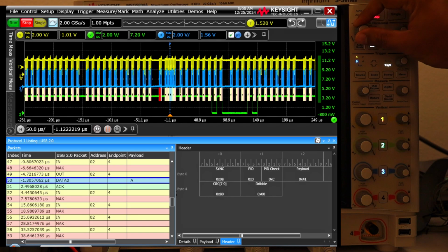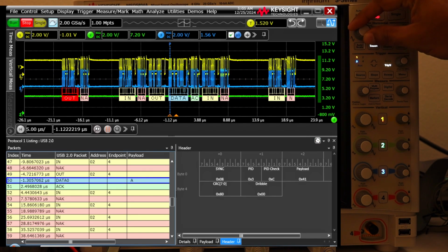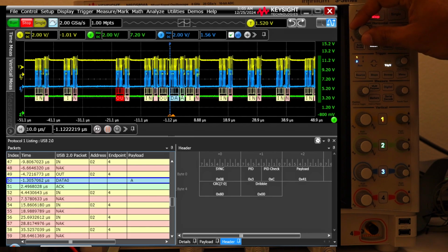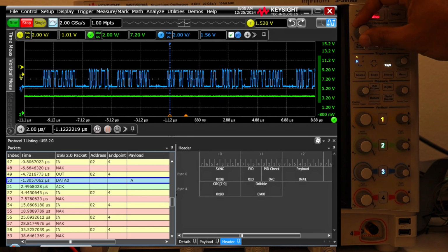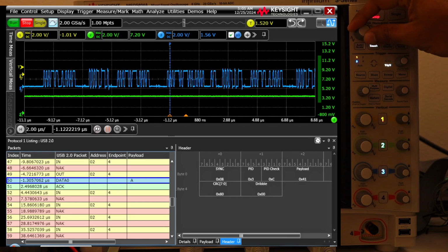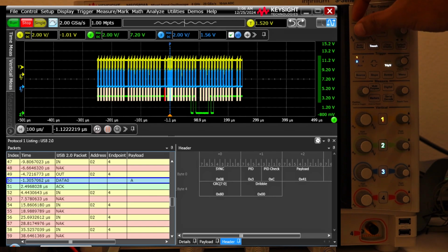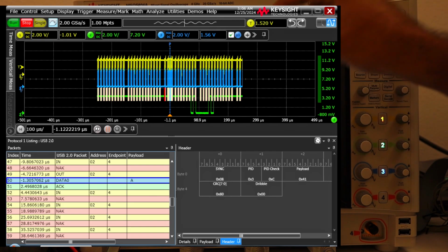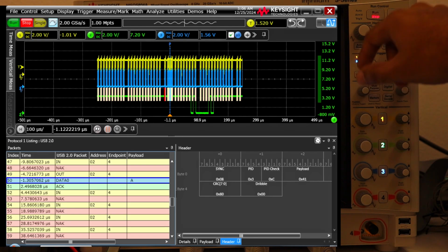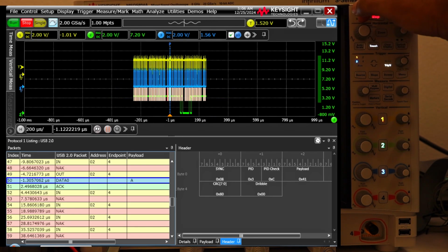If you want, we can zoom in and look at the packet itself. Data packet 0, trigger point somewhere there, data packet 0, acknowledgement, and stuff like that. So this is perfectly being received, absolutely correct. Our concern, as you see, was that this UART packet is being looped back. So we should see somewhere down the line on the bus that the same data packet 0 or data packet 1 with payload A should get back.